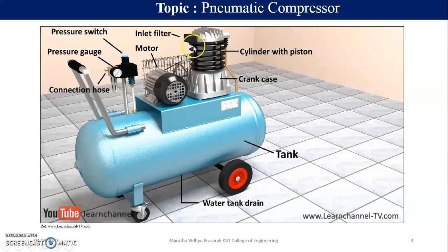What is the purpose of the inlet filter? The compressor takes air from the atmosphere, compresses it, delivers it to the tank, and it is stored in the tank. There will be dust and other particles which we don't want inside the piston, which may block the inlet and outlet valves and can even damage the piston heads. To avoid all this we use an inlet filter.